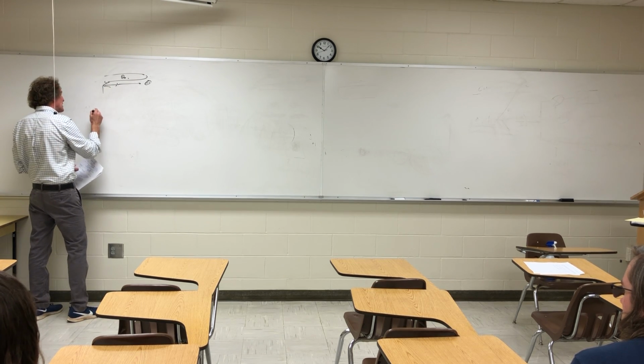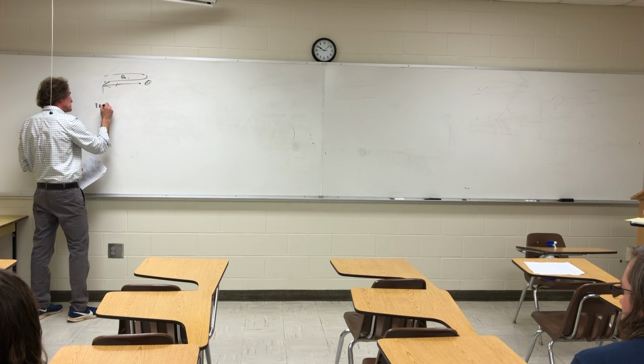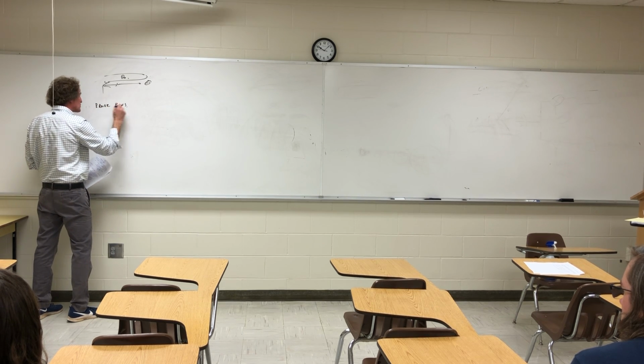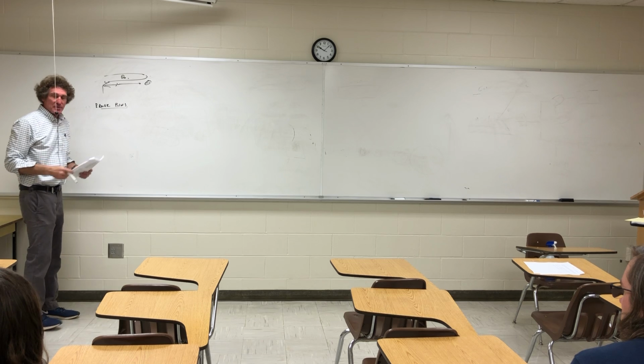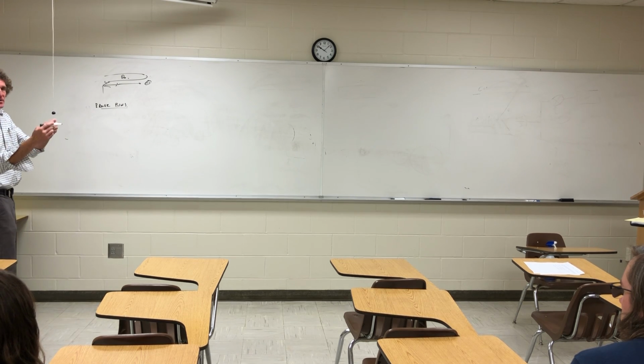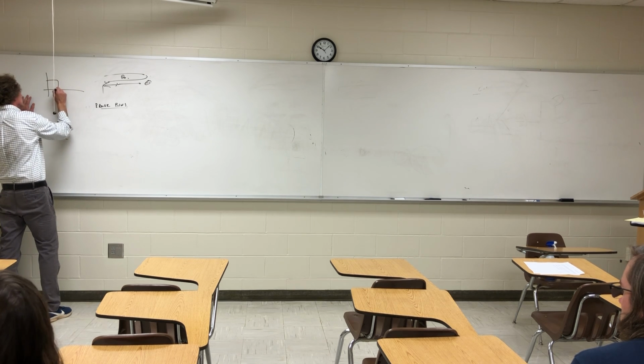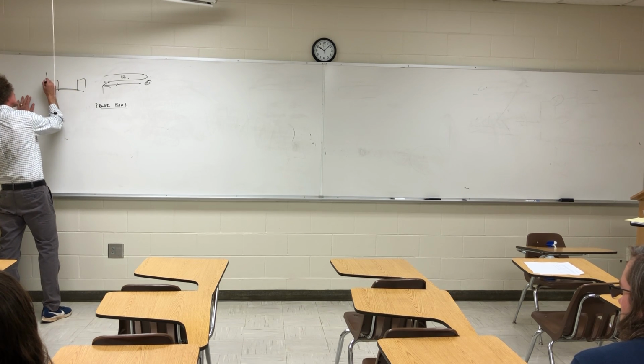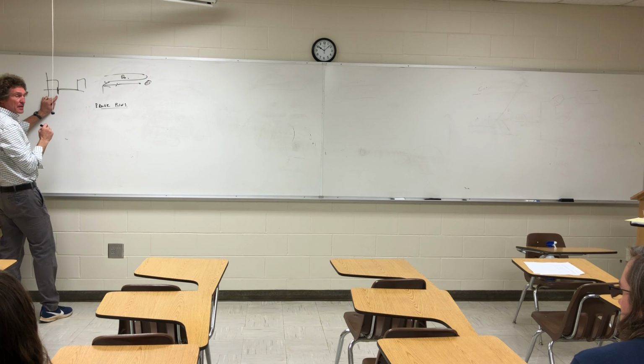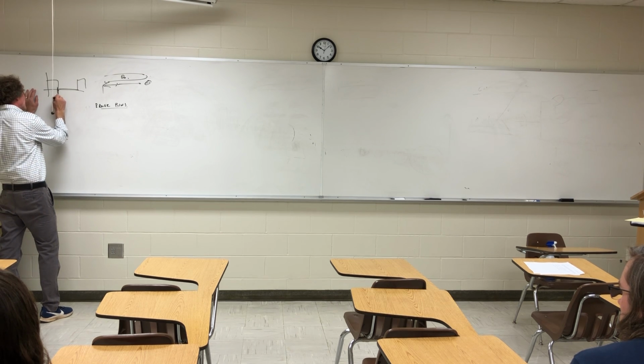Now, when it's coming back here, there's a term that's used, range bins. These are not Doppler bins, these are range bins. And here's what's happening. I send the signal out, and as soon as this part of the signal is done, once I'm at this point right here, call this time, now I start listening all through here.